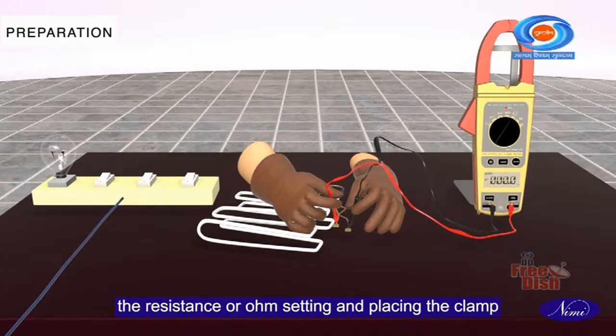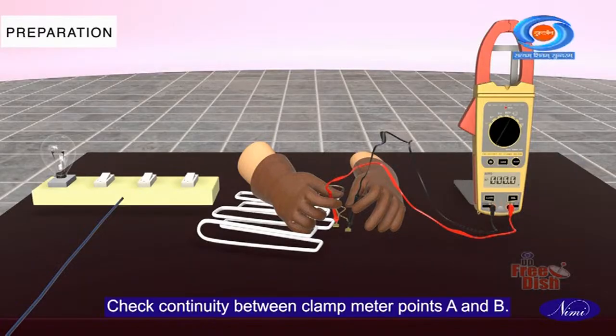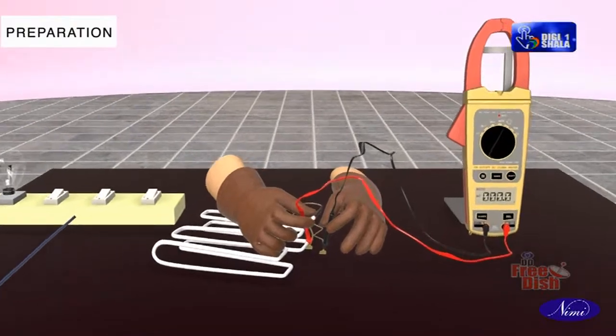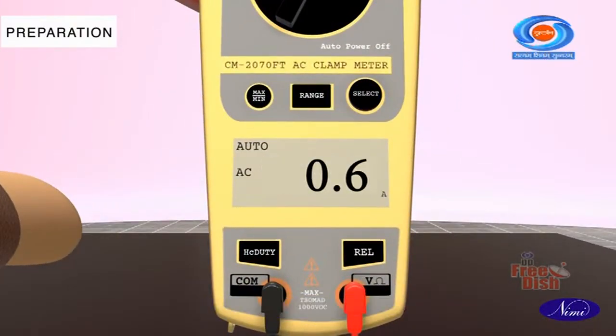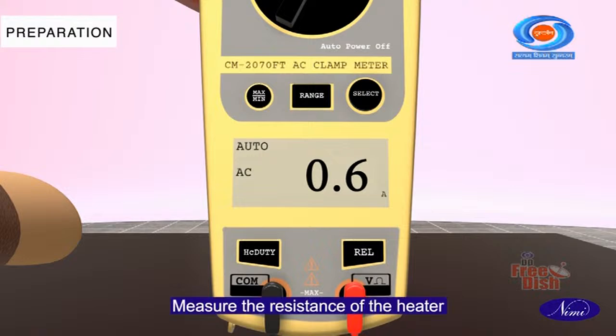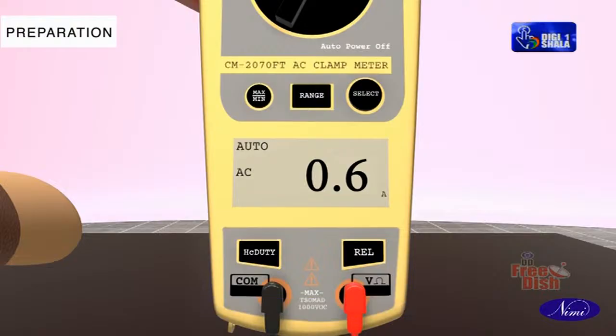Perform a continuity test to check if the defrost heater is functioning by setting the clamp meter to the resistance or ohm setting and placing the clamp meter probes on each end of the heater element. Check continuity between clamp meter points A and B. The heater has continuity. Measure the resistance of the heater and document it in the table.